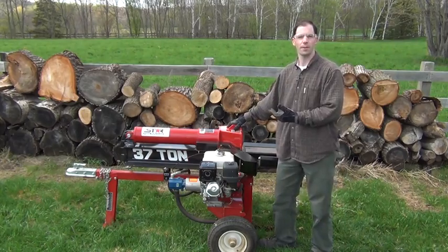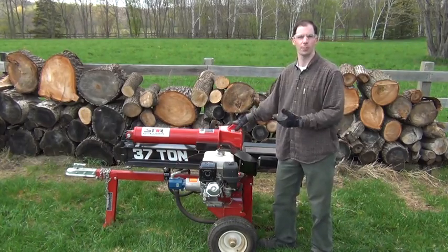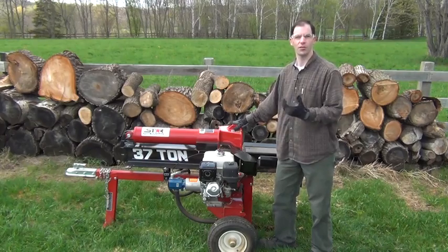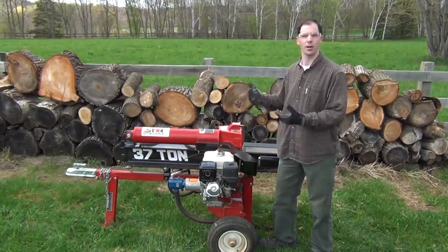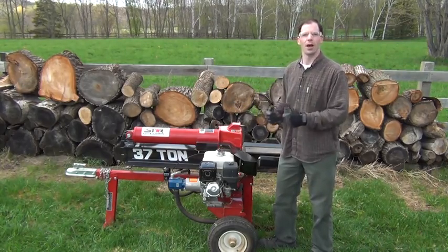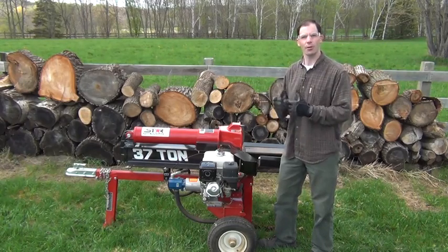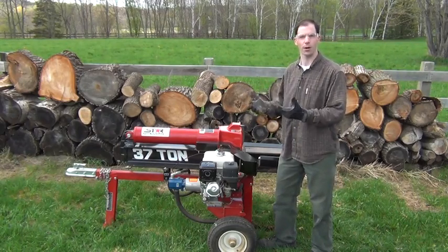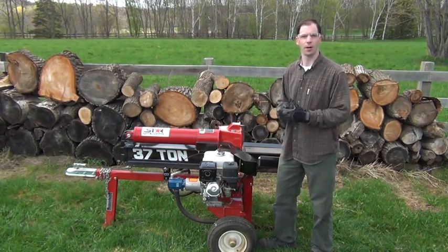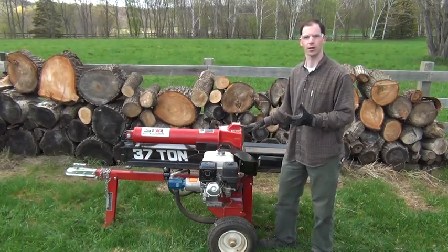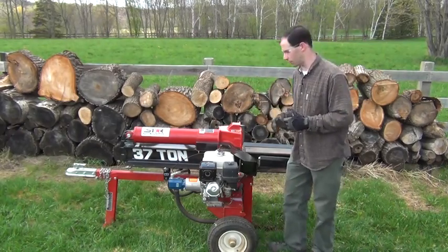And you're going to see that the speed of the actuator, of the piston, is going to increase as the engine speed increases. As we're increasing the angular velocity of the pump, we're increasing the flow rate and therefore the speed of the cylinder. And then lastly, I'm going to explore how the flow rate of the pump is dependent on the hydraulic pressure. We're going to increase the hydraulic pressure by putting a log in here. So let's look at these 3 different things.